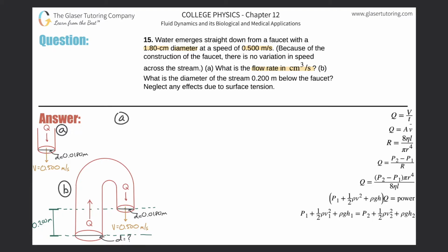You're thinking about how these variables are related to one another, and they give us a velocity and a diameter, which probably tells us we could find the area. And they're asking for Q, so I'm going to start with this equation over here: the volume flow rate will be equal to the cross-sectional area of the tube multiplied by the average velocity flowing through that cross-section. So in order to find Q, I need to know these two pieces. Let me expand on the area first. The cross-sectional area of a tube is a circle, so this becomes pi r squared. Then multiply that by V.